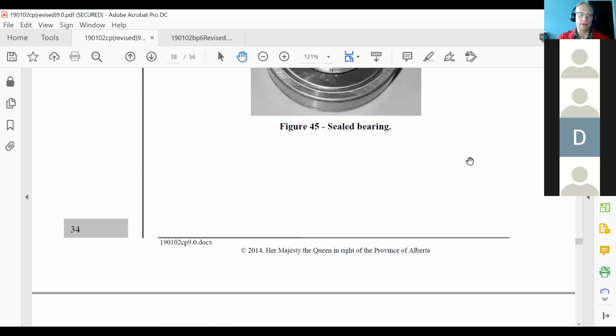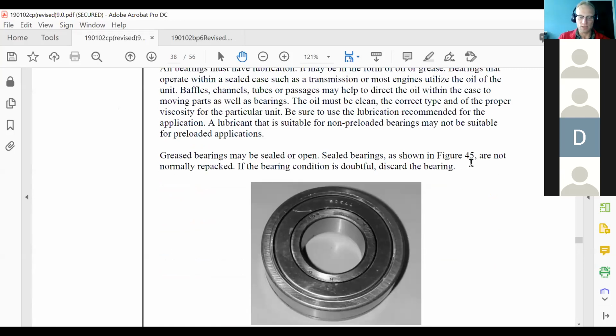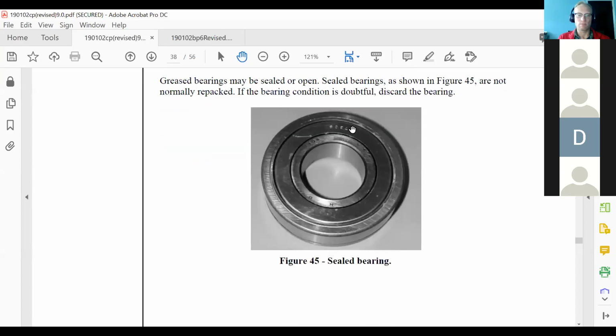Now when we're lubricating bearings, a lot of times for us it's going to be oil lubrication. So typically we install bearings and they're going to have an oil film on them. It's pretty standard. If it's a grease packed bearing, it's a little bit different. We have to make sure we're packing them correctly. But oil lubricated bearings, typically we install them so they have a little bit of oil in them. And then once we top up the reservoir, that's going to supply oil to the bearings. Any bearings that are grease, that are permanently sealed like this, typically you're not repacking them. Now, have I seen some weird things done? Yes, I have. Is it the best? No. But sometimes in a pinch, if you've got to turn this grease bearing into an oil bearing, it might work to get you home.